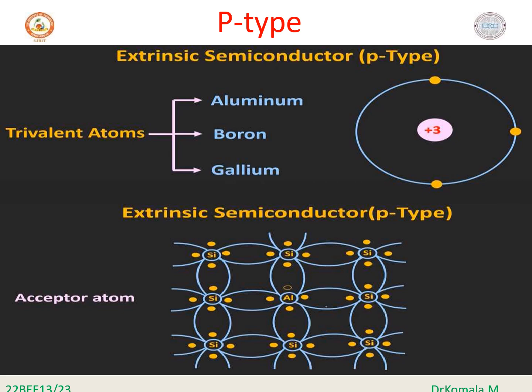Since holes can be said to have positive charge, the acceptor doped semiconductor material is referred to as a P type semiconductor. Like the N type, the material remains electrically neutral because the total number of orbital electrons in each impurity atom is equal to the total number of protons in its atomic nucleus.